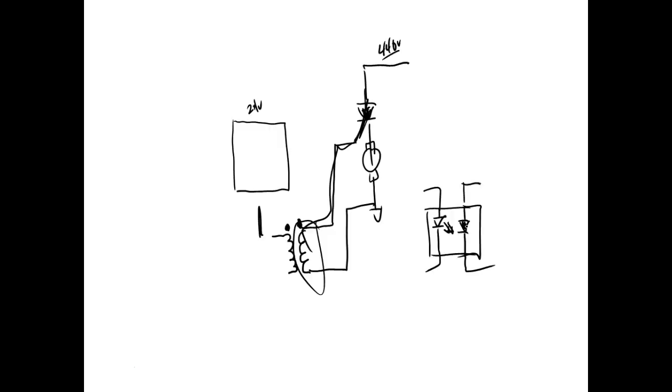You just screw up the little optical isolator, or you screw up your pulse transformer. You know? We'd like to sacrifice a $2 part a lot faster than we want to sacrifice a $2,000 part, right? Because if you let that 600 volts or 440 get inside a PLC, it's going to do what? It's going to blow that thing up.